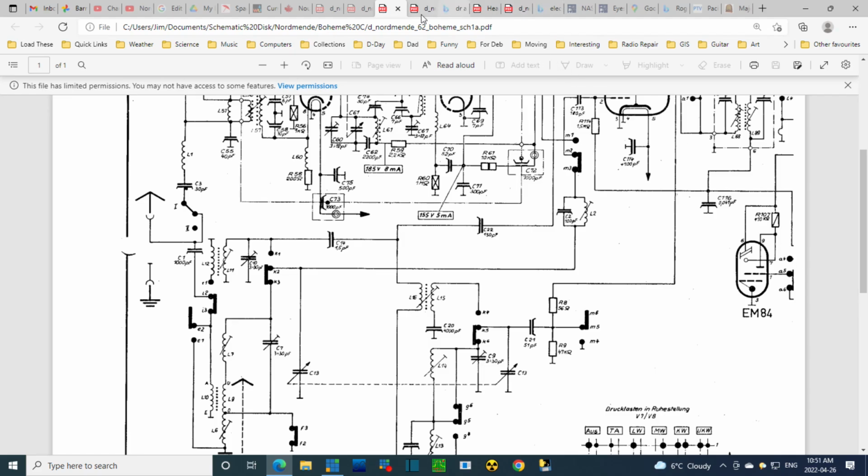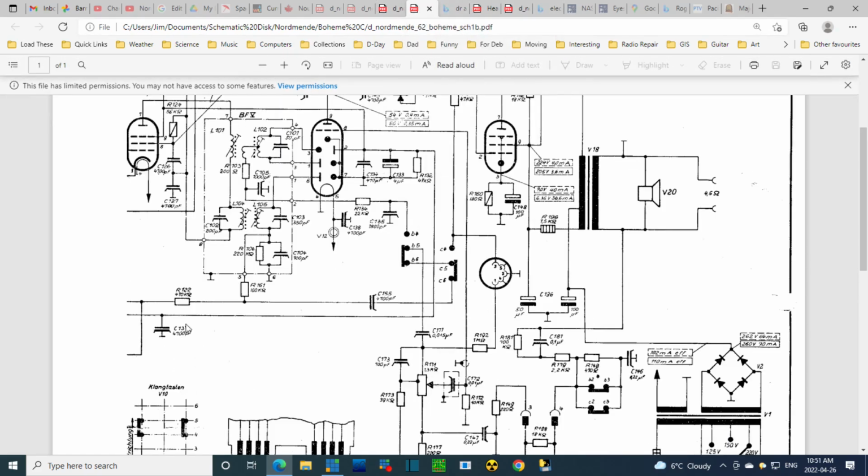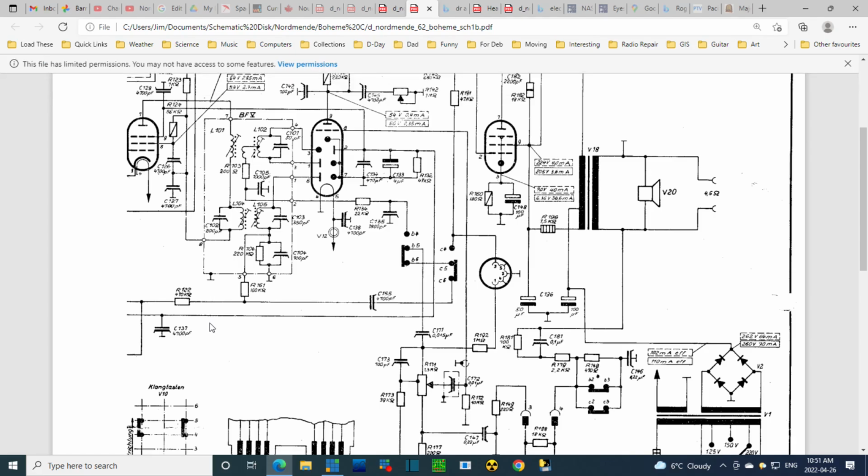Let's go back to the other schematic. I should tape these together, but it's a little hard to do on my computer here. So it's either this or this. This one is the AM side, and this one, no surprise, is the FM side. So right at the switch, things change. The radio operates with a different AVC voltage source. Okay, right at the switch.